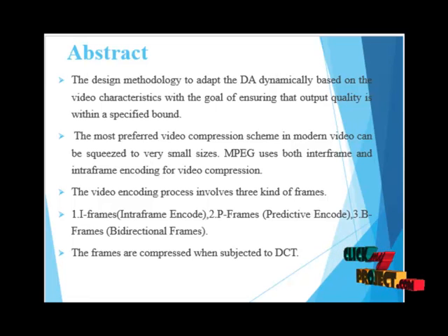Different approaches for approximation include error introduction through voltage overscaling, intelligent logic manipulations, and circuit simplification using CAD based optimization techniques. These methods can introduce simplifications by replacing adders with approximate computing adders, or by deleting some of the transistors, which introduces minor errors.